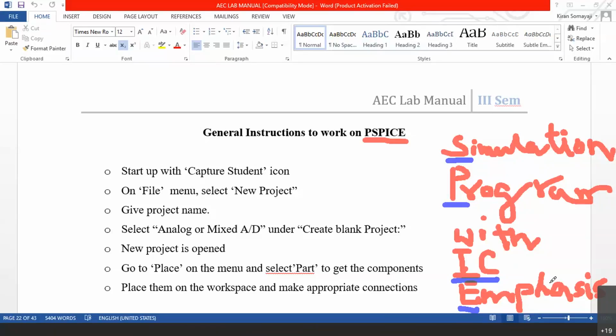Yeah, formula in the sense, in the theory class, we have already seen how a BJT can be modeled using small re or using hybrid parameters. Now SPICE will have a bigger mathematical model of all the devices, and it will have matrices inside. Actually, all the simulation programs perform a lot of matrix computations, which means the characteristics of the device are stored, even though we mention them as equations, all those equations are stored in the form of matrices.